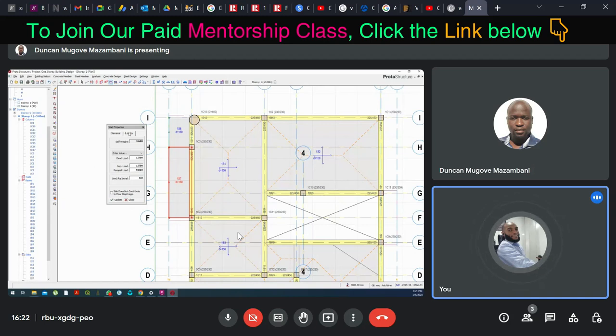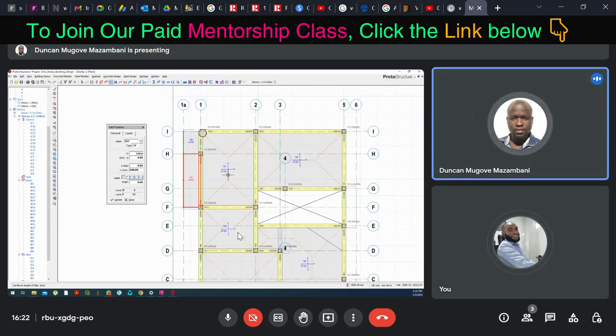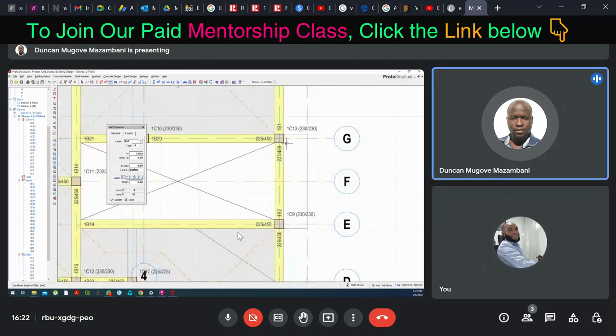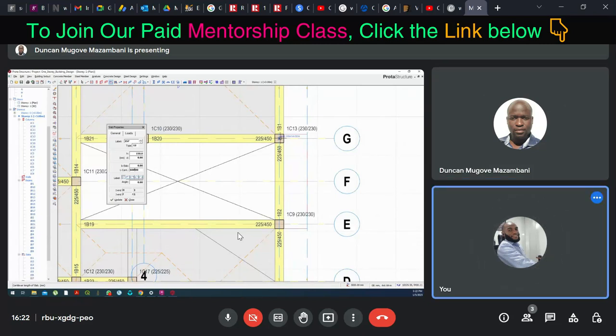So now go and change your distance to 600 for the other side. Length of cantilever, 600 for this other side. Everything else remains the same. Column to column. Then pick outside. That's fine. Now go and check your 3D view. Escape and take a 3D view.